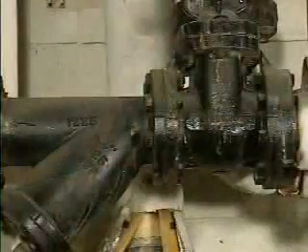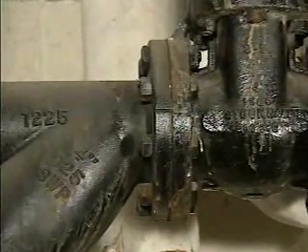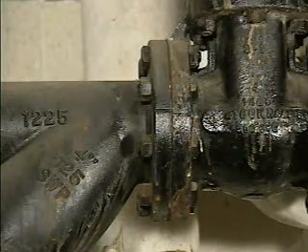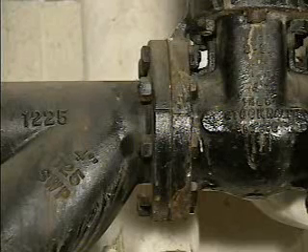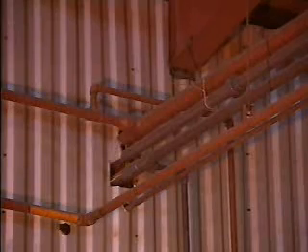For this reason, it is often used in high pressure and high temperature systems, such as hydraulic systems that push and lift heavy loads. Another characteristic of carbon steel is that it's less brittle than other materials, such as stainless steel, so it's able to absorb vibrations. Therefore, it is well suited for systems that generate significant vibrations, such as in vibrators, used to make anodes in aluminum manufacturing processes, lifts, and large gearboxes attached to motors or turbines. Because it is susceptible to corrosion, carbon steel is generally used with non-corrosive gases and liquids.